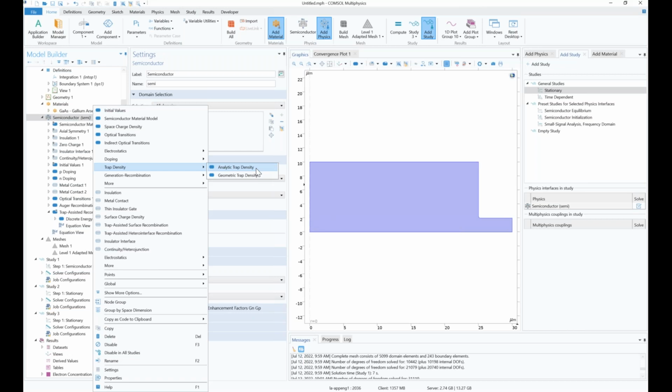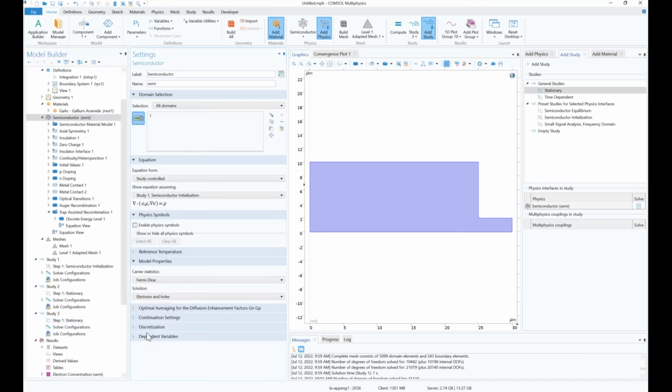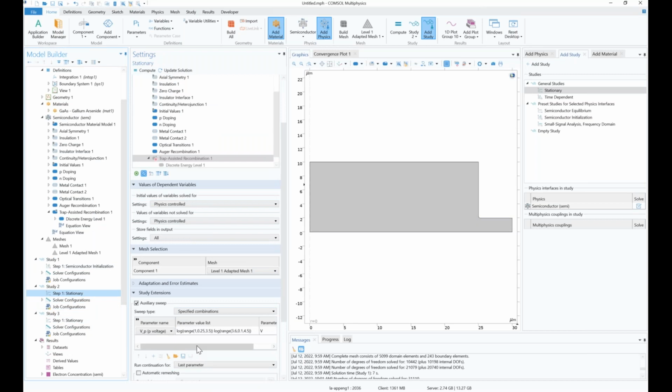And if you also add this trap density in your model, you also need to slowly increase it and run this so-called continuation. That's usually the very basic tips you might use for your convergence case. I'm sorry, I think time is up.